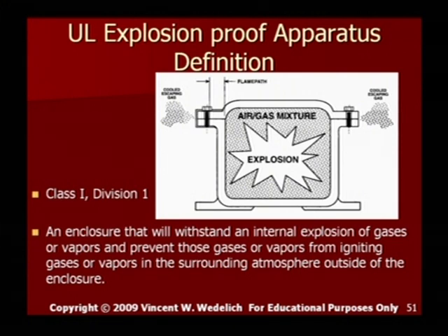And that cover is extremely heavy. So if you have an area or a site and you're a maintenance guy and you notice that some bolts are missing from some of these NEMA 7 boxes, make sure you get them all installed with the proper bolts from the manufacturer. Don't substitute those bolts. You have to get them from the manufacturer.